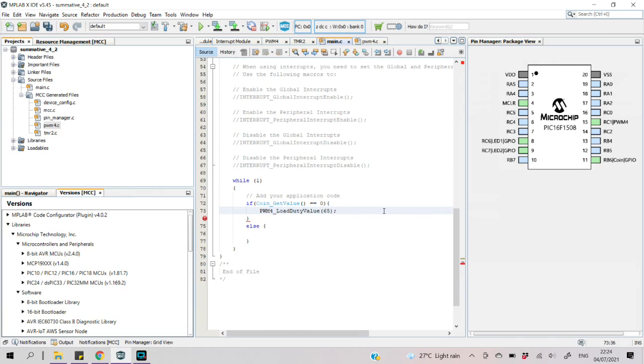So as we can see, by computing its duty cycle and its equivalent PWM DC value for the servo motor, it ranges from 30 to 65 respectively, where 65 is the negative 90 degrees, while the 30 is the positive 90 degrees.